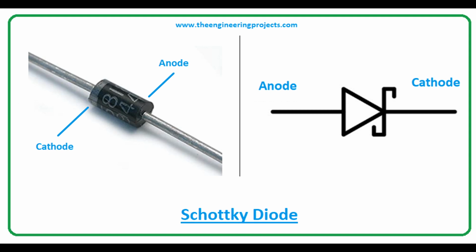In a forward-biased diode, the positive voltage is applied to the anode, the p-type region in a p-n junction diode or the metal contact in a Schottky diode, and the negative voltage is applied to the cathode, the n-type region in a p-n junction diode or the semiconductor region in a Schottky diode. This forward biasing reduces the potential barrier at the junction, allowing majority charge carriers, electrons in n-type and holes in p-type, to move across the junction and contribute to the flow of electric current.